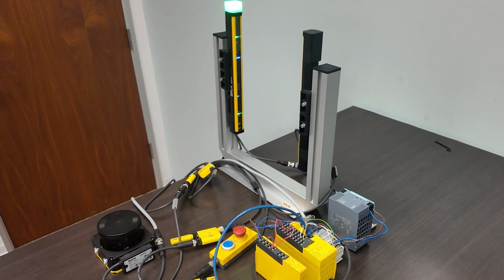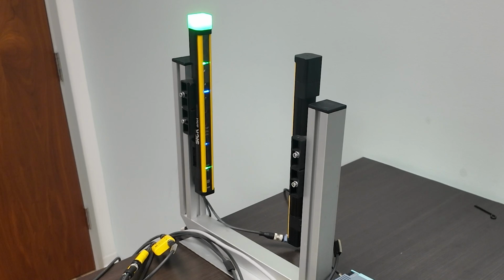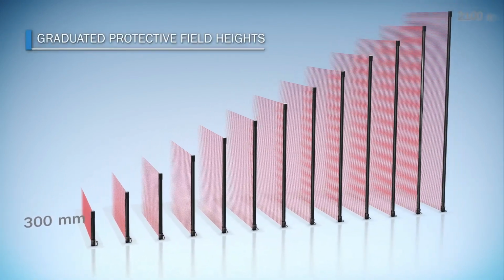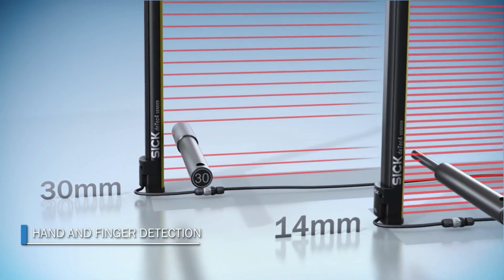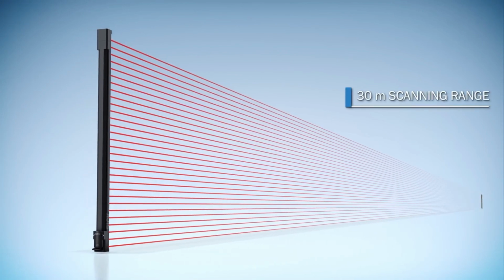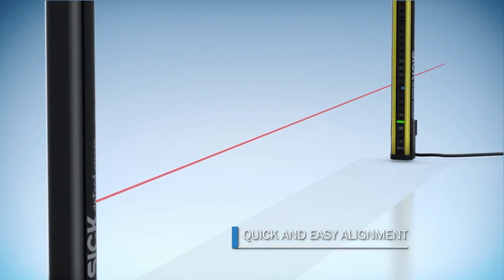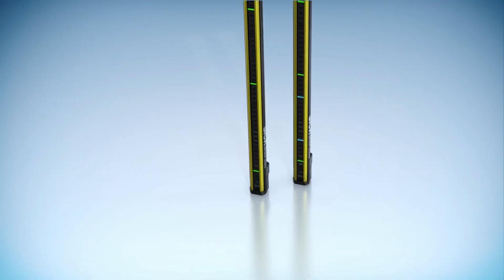Secondly, now we have a light curtain, which is from the D-Tech 4 family of SICK light curtains. Usually used in access protection, point protection. And what makes this light curtain really special and unique is firstly, no blind zones on this height profile. And then we also have inbuilt lasers which help you with the alignment. Along with that, we have something called system plugs on them, which have a lot of different functionality, such as muting, smart box detection, and they also come with NFC, and that is all inbuilt on the hardware.